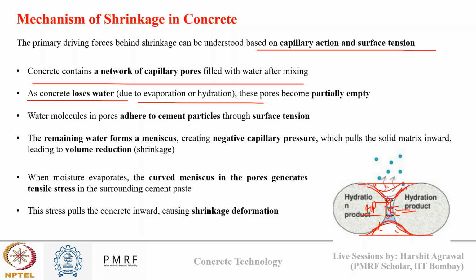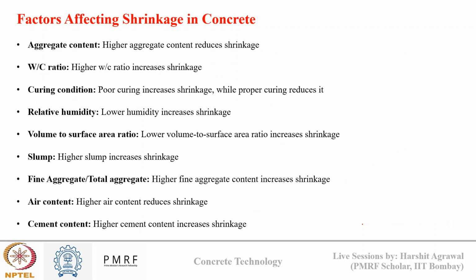Okay, and this meniscus creates negative capillary pressure on the cement paste, and it tries to pull the cement paste towards each other. This inward tension force that is applied on the hydration product leads to shrinkage deformation in concrete. Different concrete factors can affect shrinkage differently.